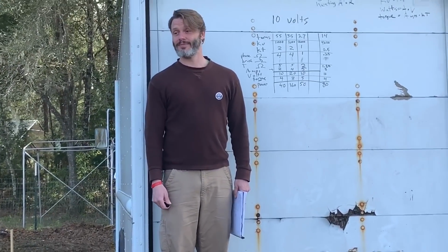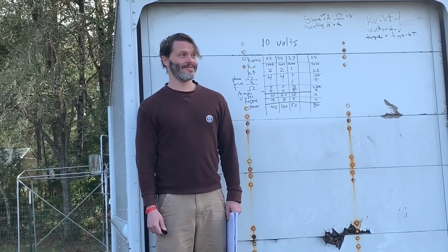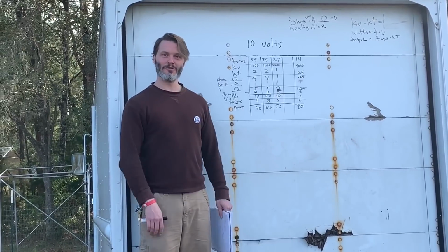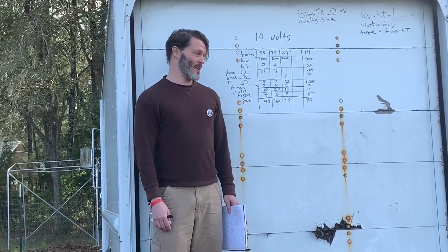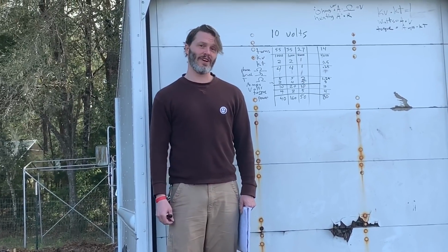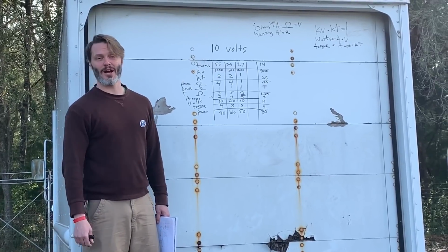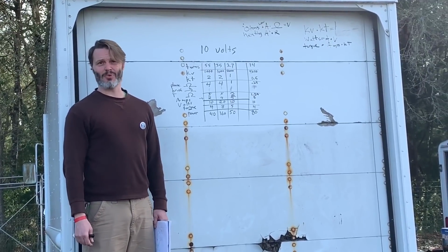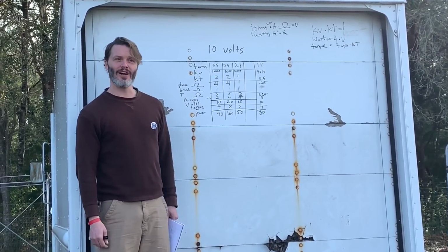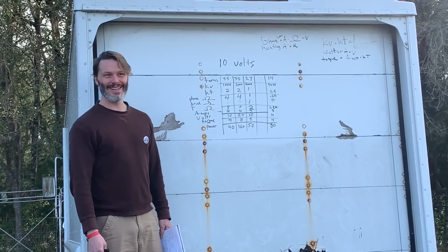Anybody else? No? We good? Y'all kind of understand now? There's going to be a golden zone for torque, essentially. It's either going to be the ESC that's hurting, or it's going to be the brushes that are hurting, but if you push too fast, it's going to hurt you. Or if you go too slow, you're not producing as much torque, it's not going to be optimized. And surprise, surprise, most people like that 1800, 2000-ish kV range. And to me, it's not a surprise, but I've been doing this a while.